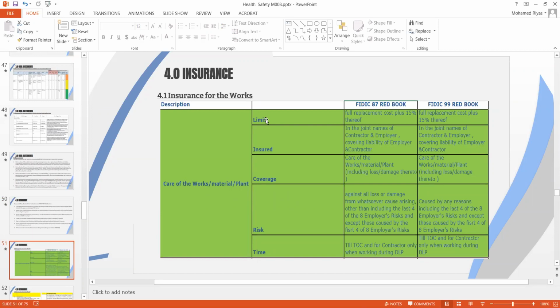So especially in a competitive nature, if you're getting the project, the cost of construction will be less compared to the period where the economy is on the higher side and all the prices skyrocket, then you'll end up paying too much. So you need to be very careful if you are experiencing a similar situation on the cycles of the economy, and if you are signing a contract which is 30 or 40% less than the price of the market peak, then you're supposed to take care, because the next cycle when it comes, if you suffer any of the risk on the CAR and the project is destroyed and needs to be rebuilt, then the insurance amount won't be sufficient. So that's why it's very tactical: full replacement cost plus 15%, the limit.